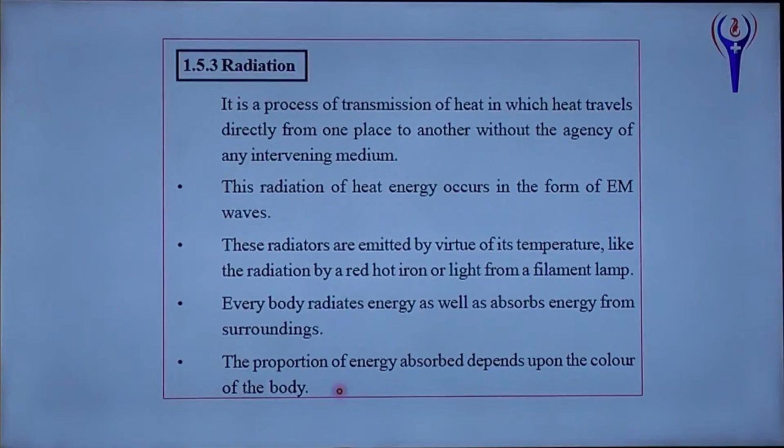Radiation. The third mode of heat transfer is radiation. Radiation is a process of transmission of heat in which heat travels directly from one place to another without the agency of any intervening medium. No material medium is necessary. The best example is solar radiation. We receive solar radiation even through vacuum. The radiation of heat energy occurs in the form of electromagnetic waves.